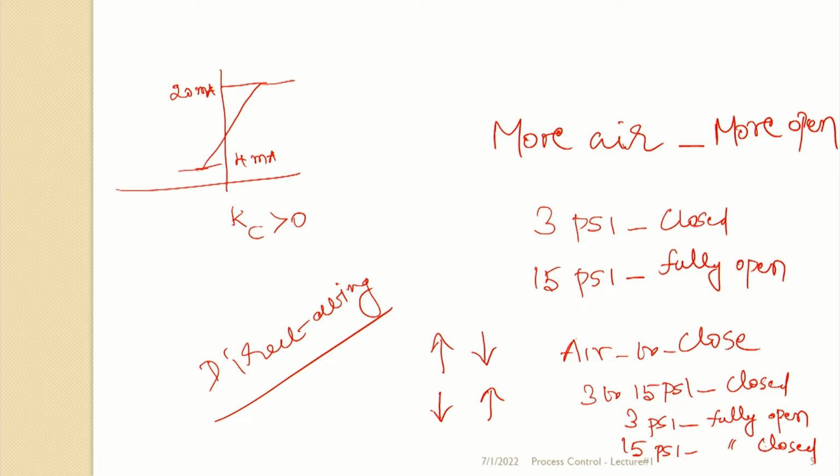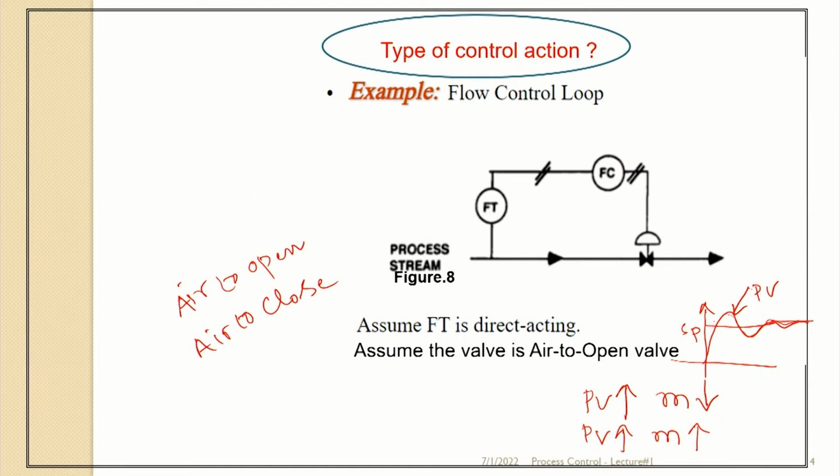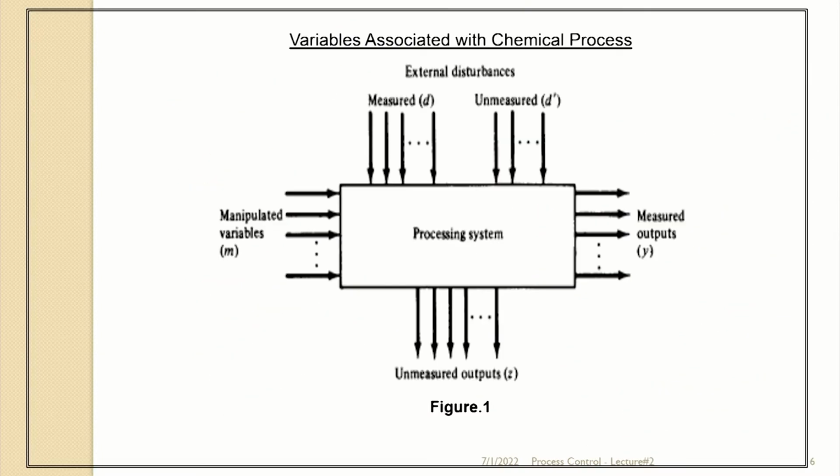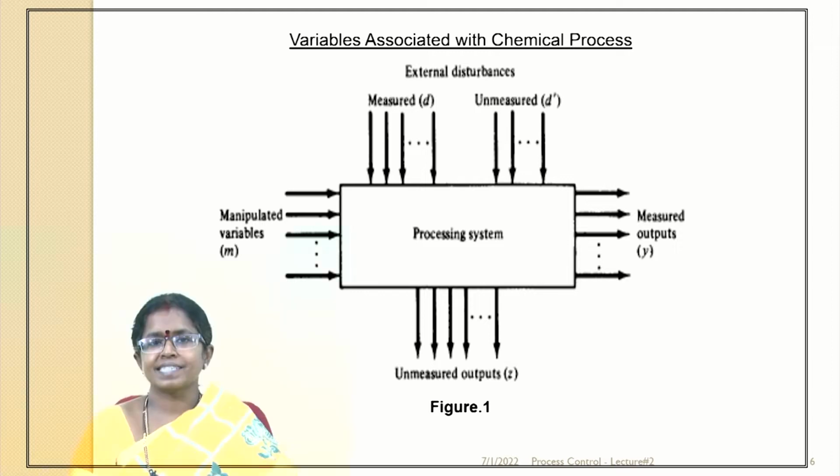Now I hope you clearly understood the difference between a direct acting and inverse acting controller. Depending upon the action of the control valve, we have to choose whether to use a direct acting controller or an inverse acting controller. Okay, now we are going to discuss lecture number 2.